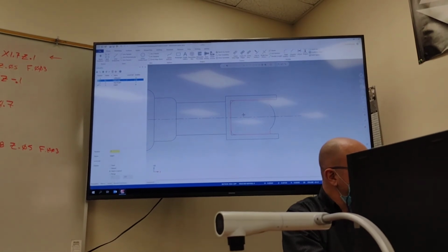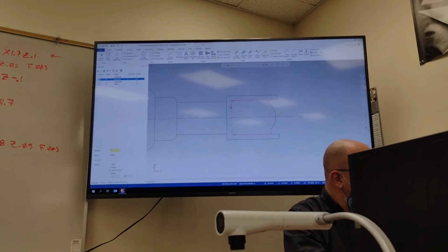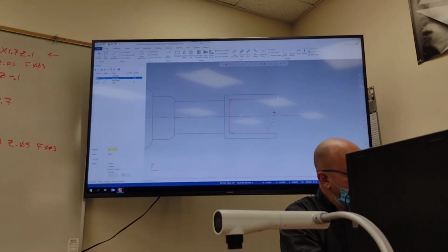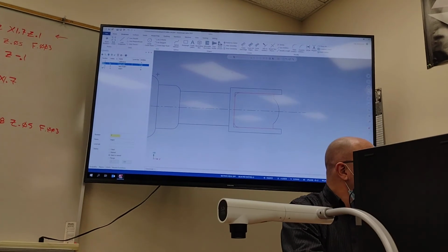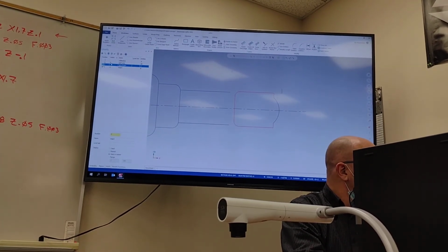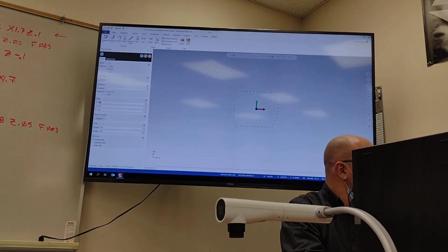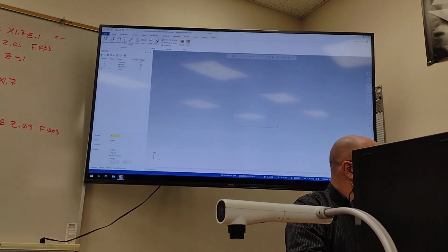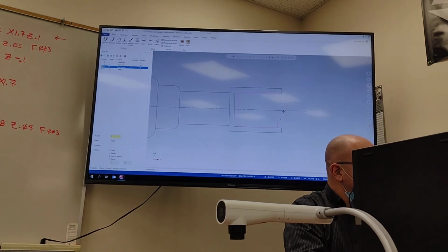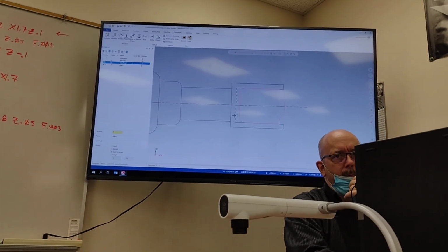As it's drawn, it looks like it's a little too deep inside the pocket here, huh? So we could do a couple things. I just kind of freehanded it, and that's how it came out. We can go back and make this arc tighter so it sticks out more. We could select everything and move it maybe 50 thousandths, and then look at it. See, it brought it up some, and at that point we would want to modify the bottom of our part number here.